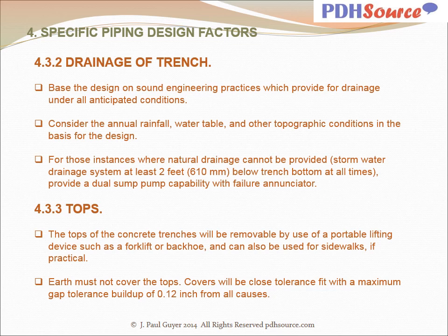The tops of the concrete trenches will be removable by use of a portable lifting device such as a forklift or backhoe, and can also be used for sidewalks if practical. Earth must not cover the tops. Covers will be close tolerance fit with a maximum gap tolerance buildup of 0.12 inches from all causes.